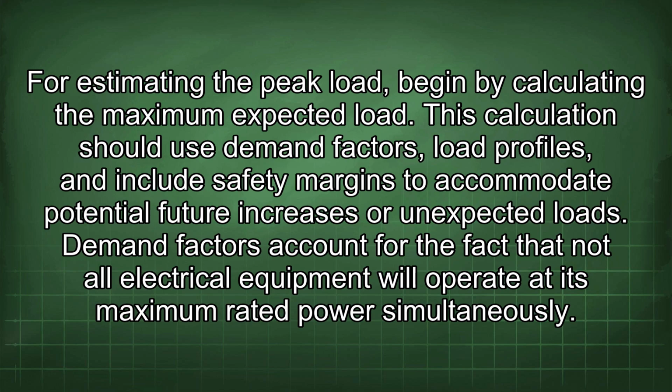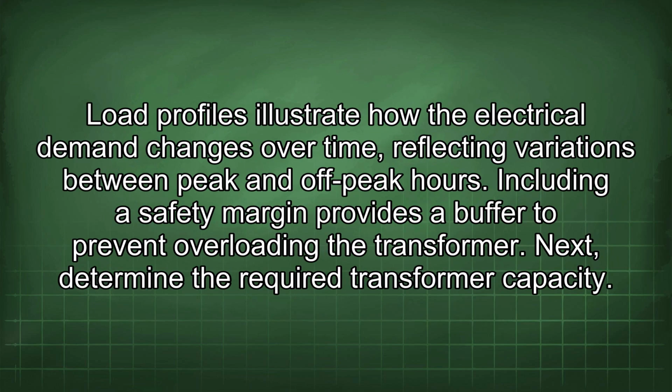This calculation should use demand factors, load profiles, and include safety margins to accommodate potential future increases or unexpected loads. Demand factors account for the fact that not all electrical equipment will operate at its maximum rated power simultaneously. Load profiles illustrate how the electrical demand changes over time, reflecting variations between peak and off-peak hours. Including a safety margin provides a buffer to prevent overloading the transformer.